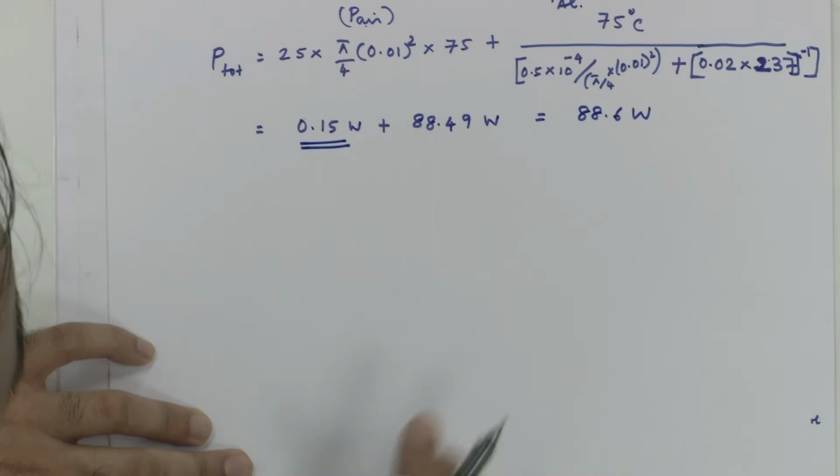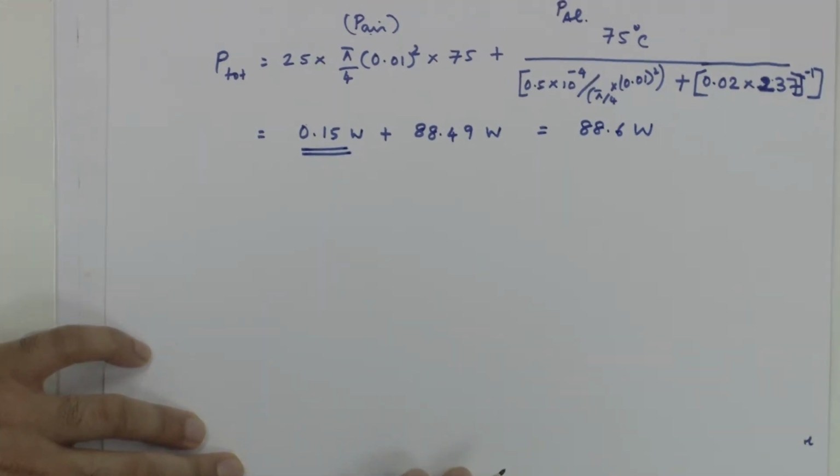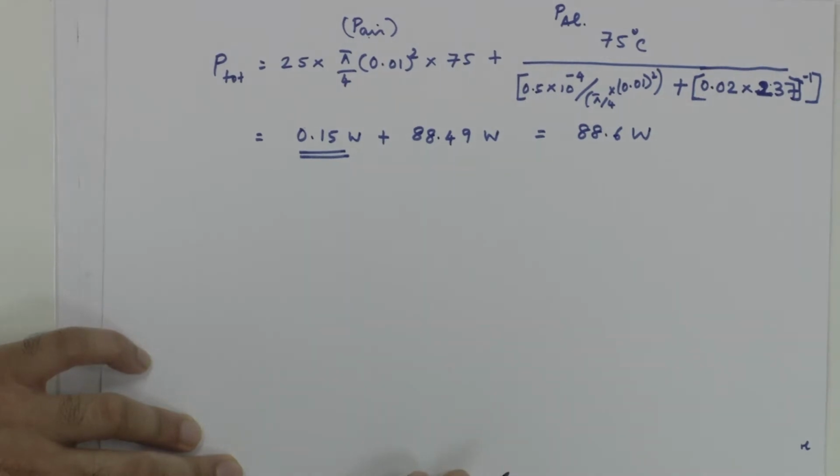The point to notice is that the top side you can easily ignore for your calculation because the area of the heat source is much smaller. When you are talking about electronics, you will find that there are many different power components in a PCB or any electronic system.